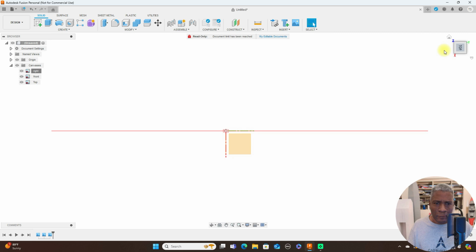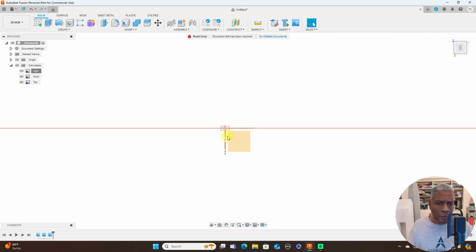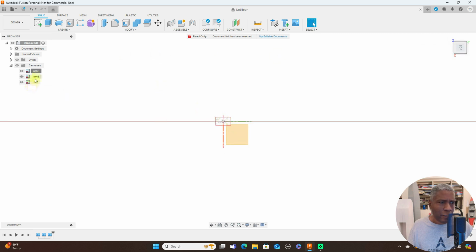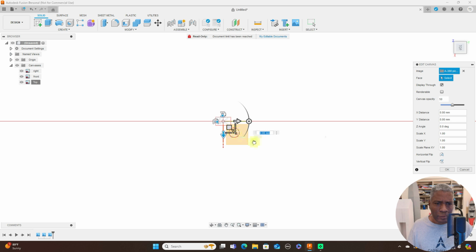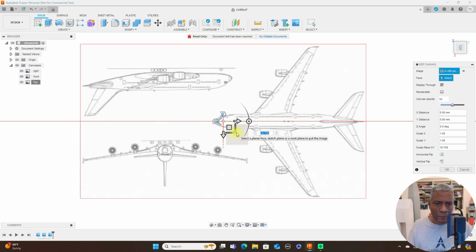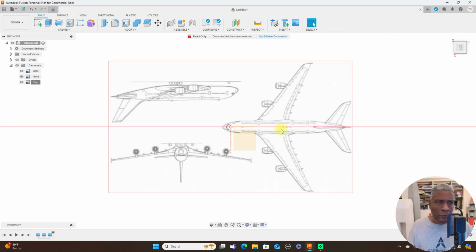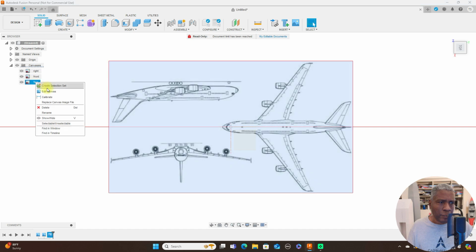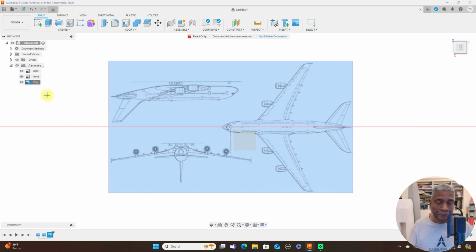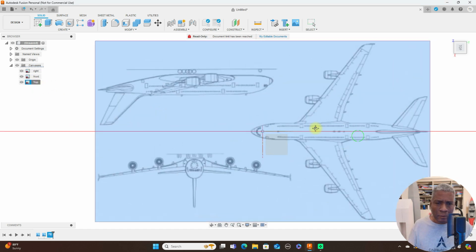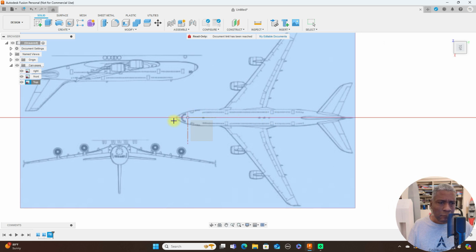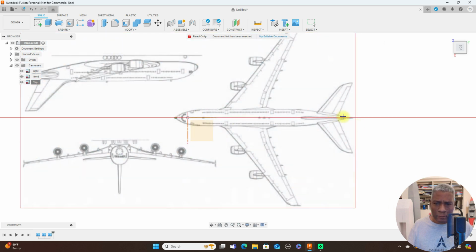Then we'd normally go to the top here. I didn't drag this out, so click on this and click Edit, and then drag this out. Then click OK, and then scale this or calibrate it as well. And make this 2 meters.